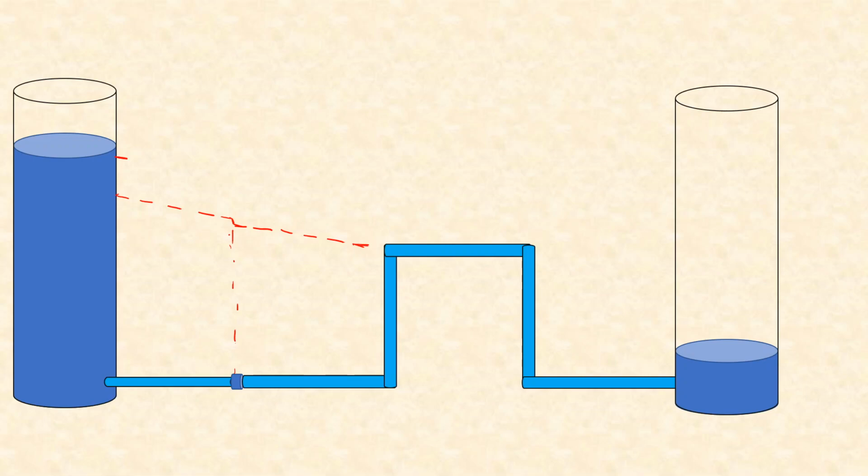and it's difficult to show the head loss in this length of the pipe, and that's because we are drawing a 2D diagram. So if we are only concerned about the variation of head in the horizontal direction only, then we can simply come to this point. At this point the head loss will be because of this bend, this extra length of pipe, and this bend. So we can subtract a significant amount of head within this small length.